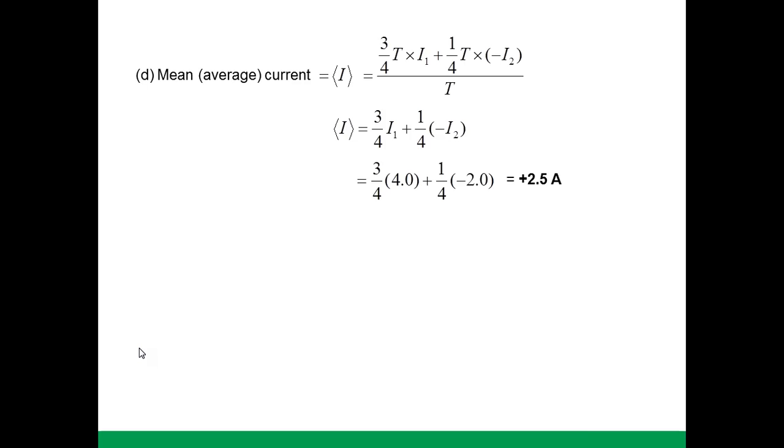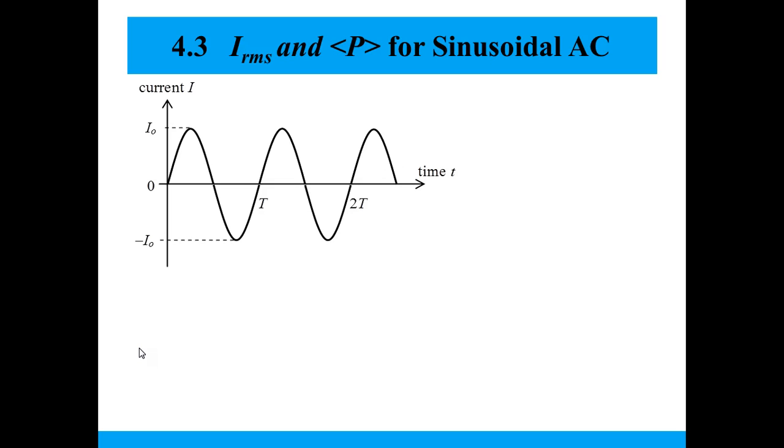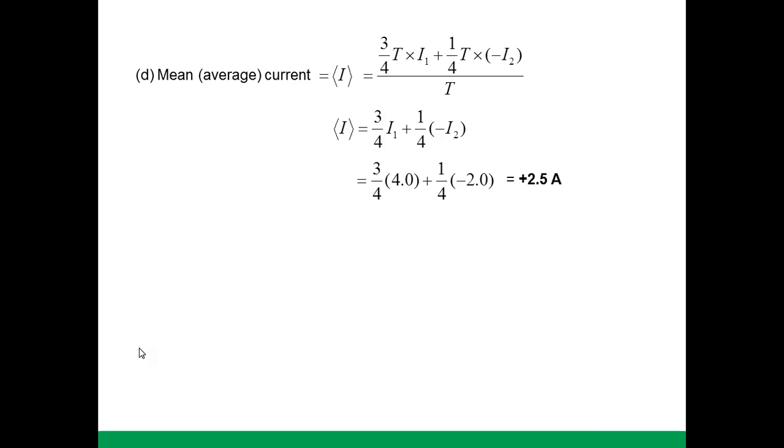That is to say, if you were to wrongly use the mean current, square it and multiply it by R to find the power, you would be underestimating the power provided to the object. This is in fact a dangerous exercise, which I will illustrate later on with examples.